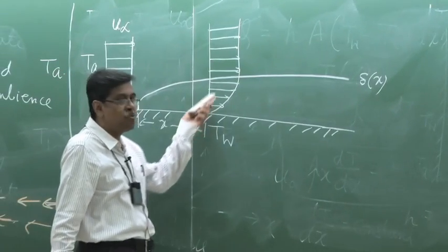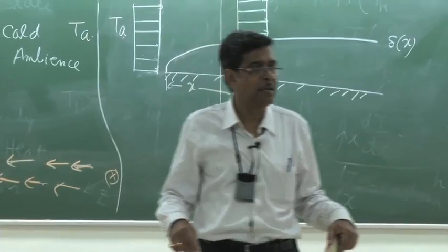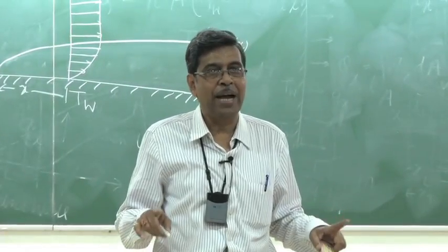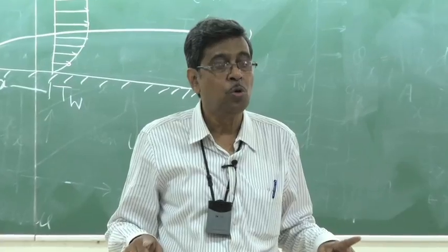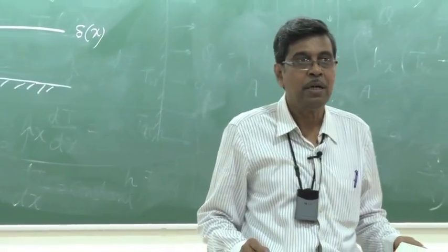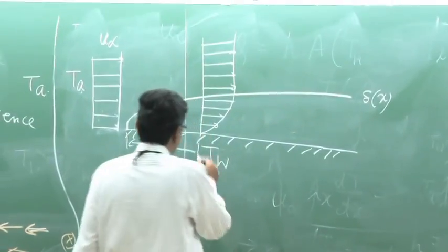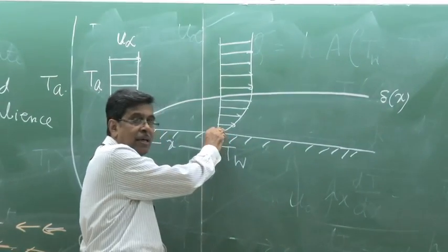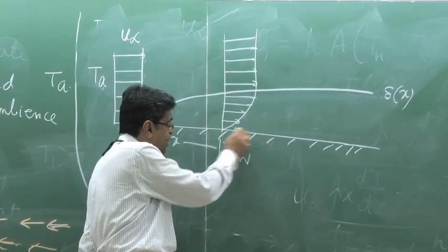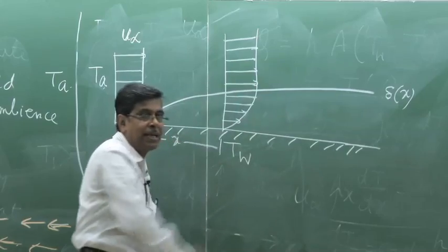Then because of this momentum transport and the momentum retention, relative affair between these two, which is manifested through the kinematic viscosity, the fluid flow is adjusted in a way that the velocity starting from zero, no slip condition because the plate is at zero, reaches the full free stream velocity after certain distance.